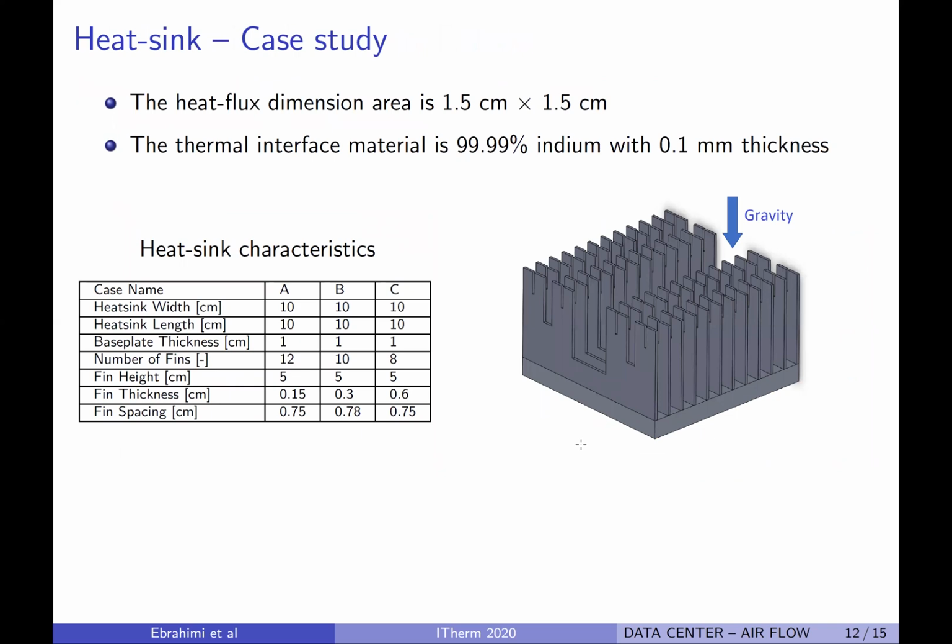We further investigate the Smith-Volterra-Cantor set, this time with the heatsink design. We consider 3 different cases. For all 3 cases, the heatsink dimension is pretty much the same. The only difference is the fin thickness and the fractal iterations.